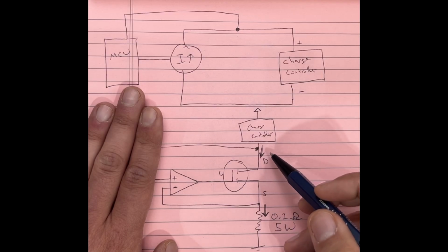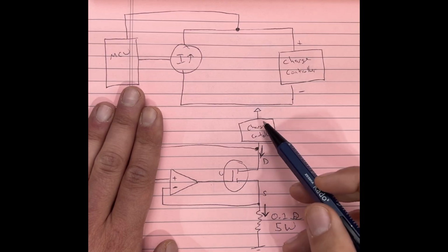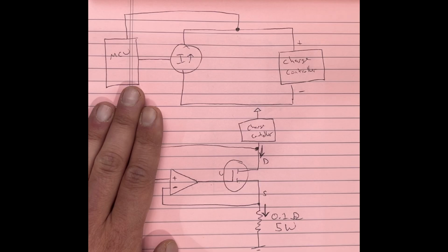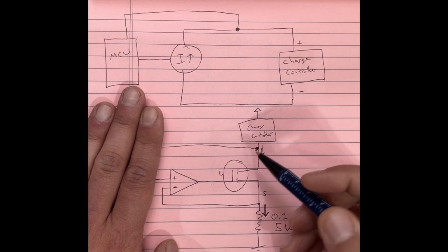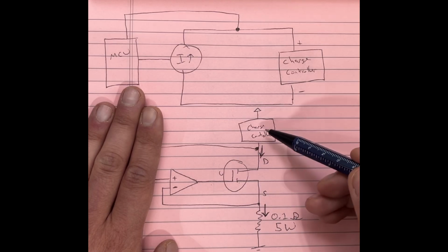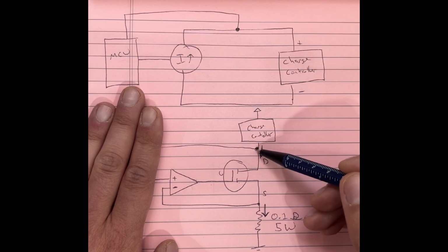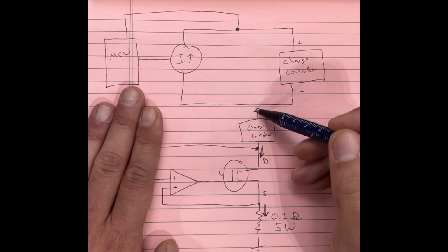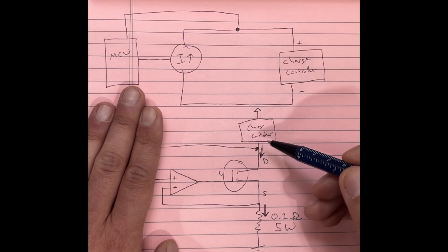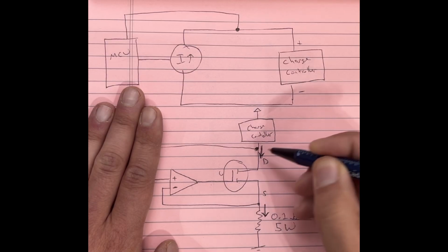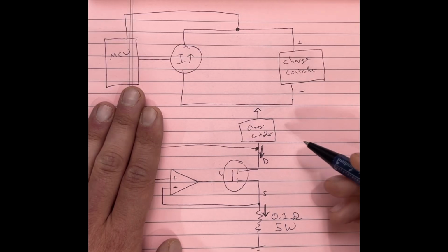And so what happens is I have the charge controller up above this entire thing. It's really a current sink. They still call them current sources, but it's really a current sink. And I have the negative terminal of the charge controller hooked up to the top of this thing. And then the charge controller positive terminal is just hooked up to the positive rail. But you know, this current is the amount of current flowing through the charge controller. So there you go. You can adjust it.